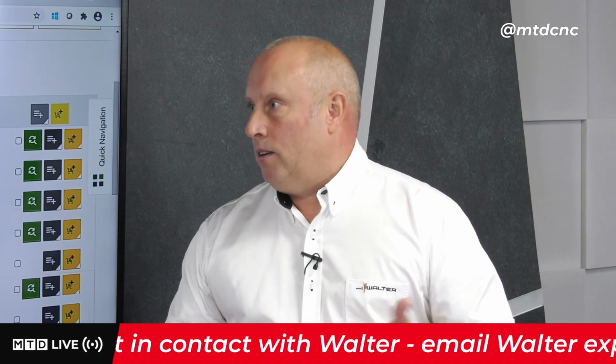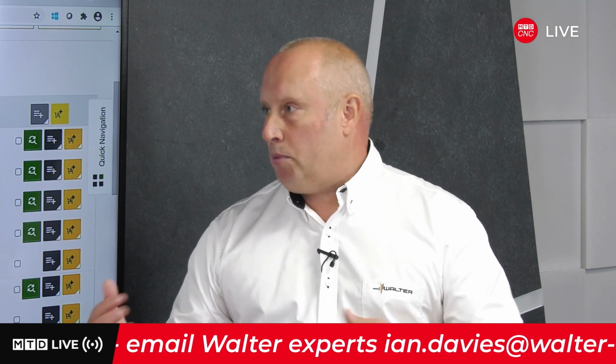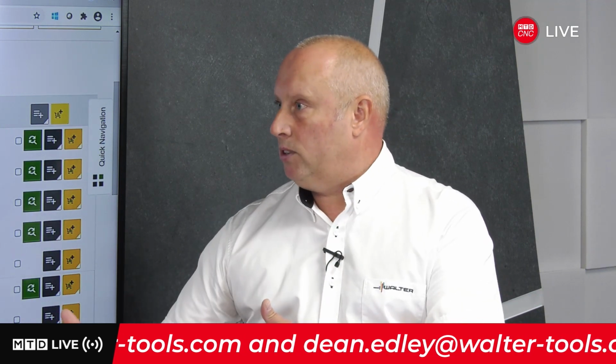So some features, if you've got a step drilled hole, 3 steps and a chamfer, Innotime would pull you 4 different tools out, whereas the customer in that industry would have a one-hit tool for that. So this is where your application engineers, your field sales engineers would be involved, and then they would be able to refine the wish list to more match the customer's requirements with the specials.